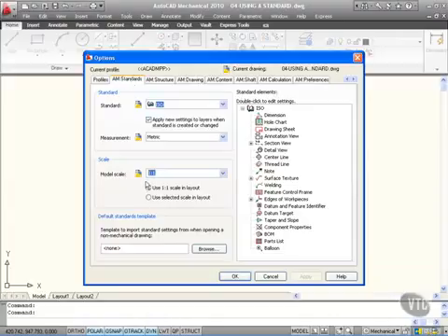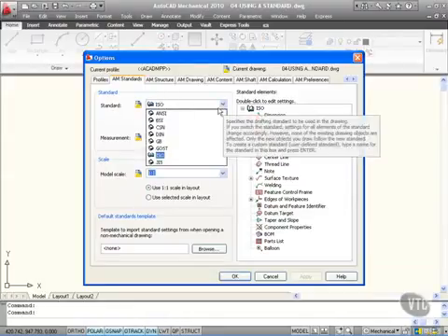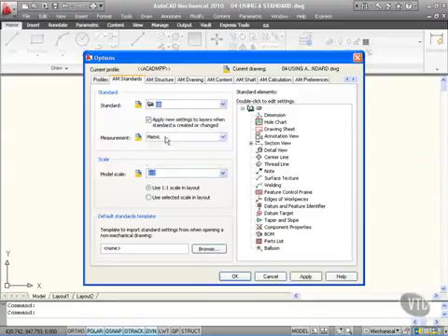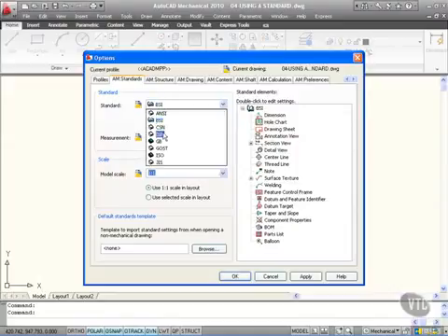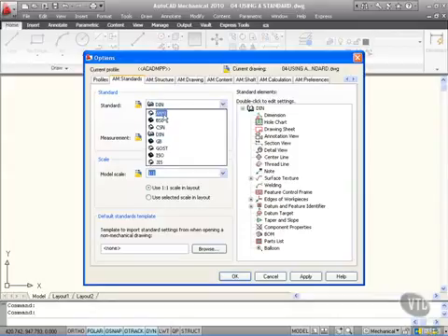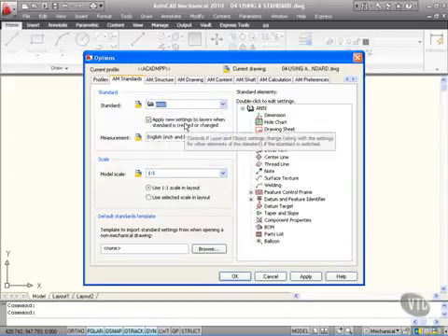When I click on there, you'll see this is where it all comes together. So, we have standard. I click on the down arrow. There's all my standards that I can use. If I go to GB, that's a Great Britain standard. If I go to BSI, British Standards Institute, and so on. You've also got DIN standards, which tend to get used in Europe, like so. And you've also got ANSI, American National Standards Institute. So you'll see that there's lots of different standards.